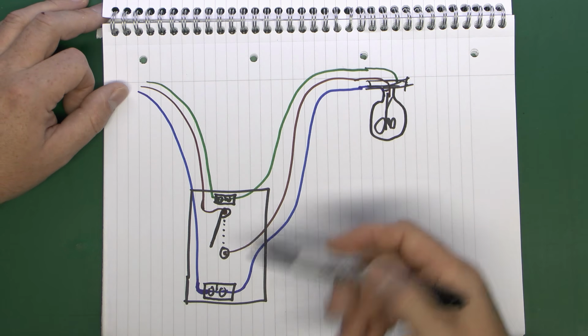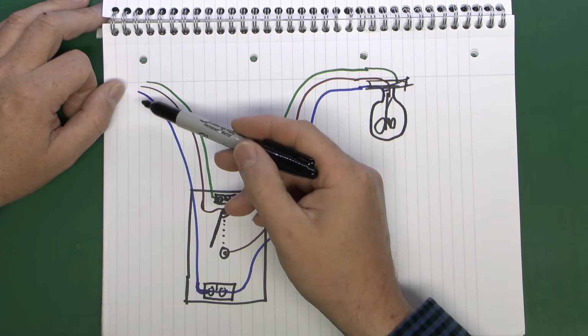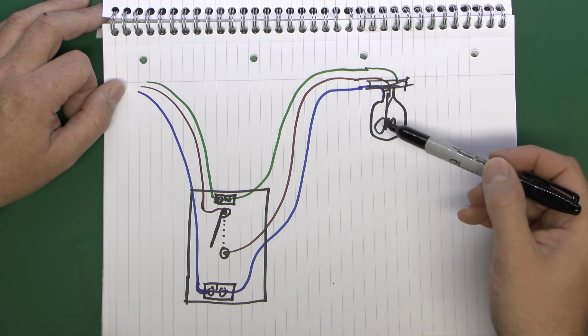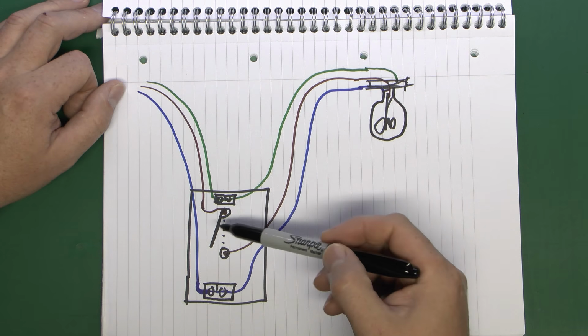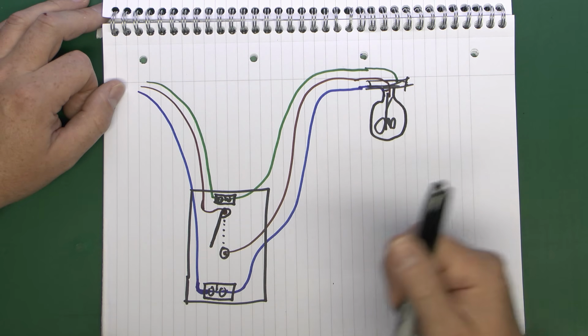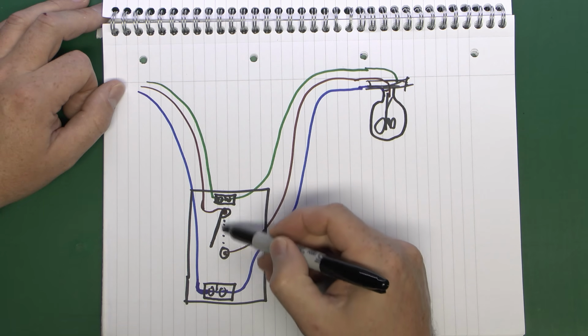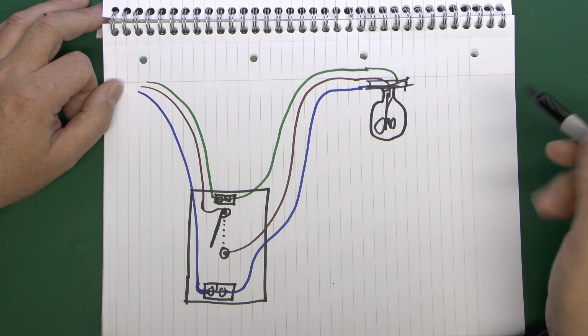So though this is a different arrangement, it's pretty much the same as we had before. Power coming in here permanently, the neutral goes straight through to the light fitting, earth goes straight through to the light fitting, but the line is interrupted by the switch here, so in this position here it's off, so no connection, so the light's not on. Of course, when it's moved into the closed position, these are joined, and the power goes through to the light, and the light turns on.